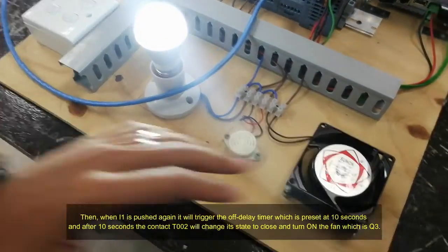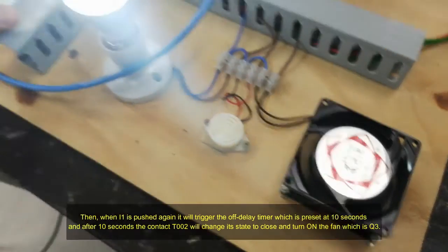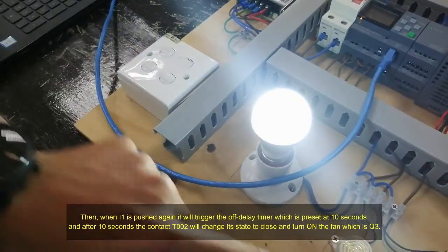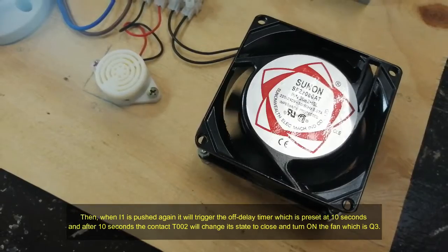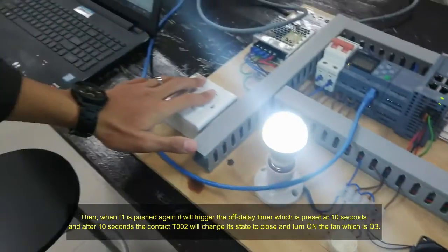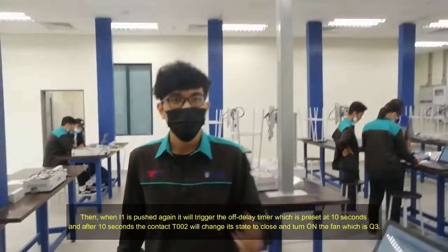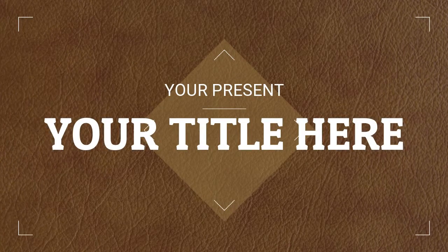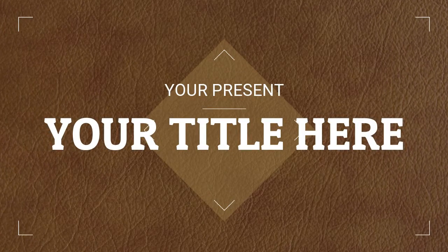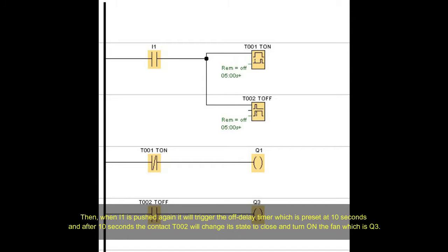Then when I1 is pushed again, it will trigger the off-delay timer, which is preset at 10 seconds, and after 10 seconds the contact T002 will change state to close and turn on the fan, which is Q3.